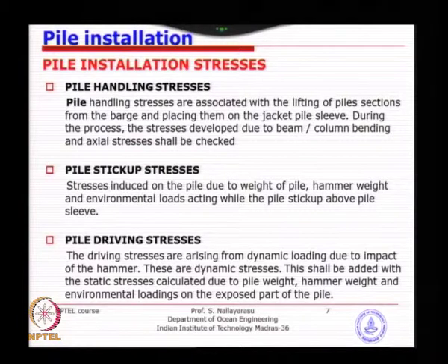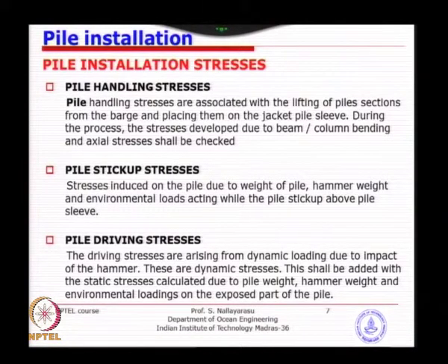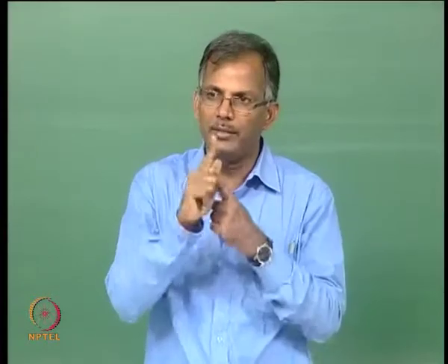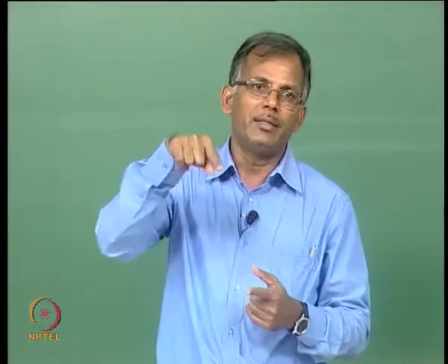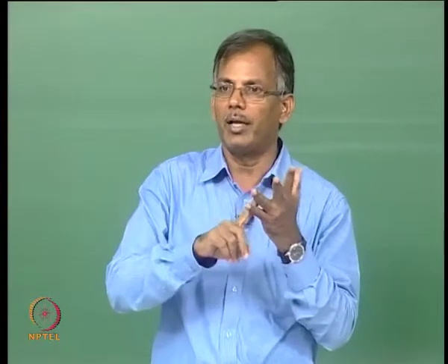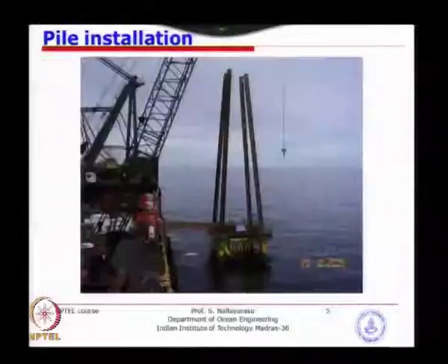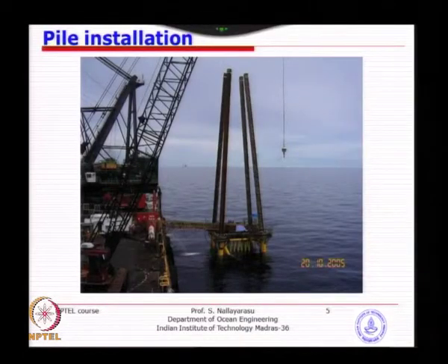So, during lifting, what are the stresses coming? Pile stick up stresses, which is what we were discussing just now, whatever the portion sticking up, due to its own weight plus the hammer weight plus the environmental loading due to wave, current, and to some extent wind. Because if the pile is sticking up, if you see this picture, so much of length is sticking up, and if a gust wind comes, for sure it will cause horizontal loading due to wind, which will cause stresses at that level, because that is where it is going into the sleeve portion.